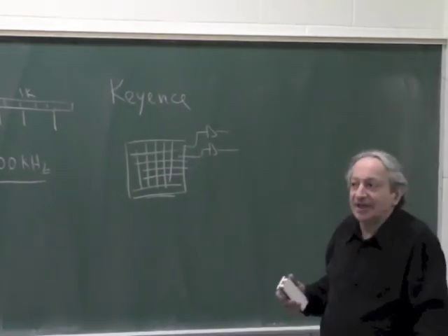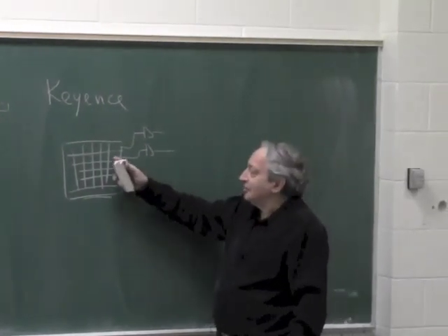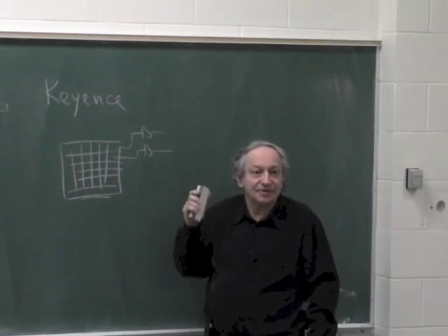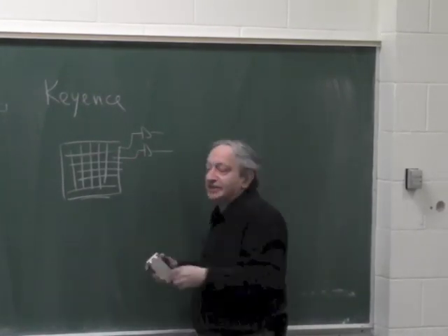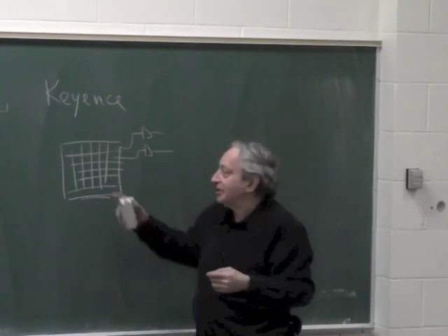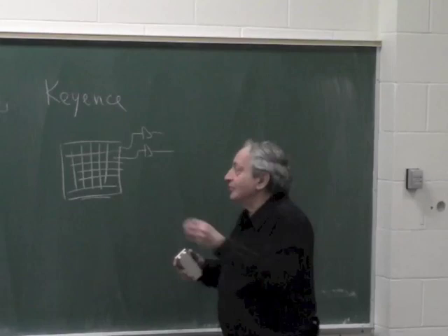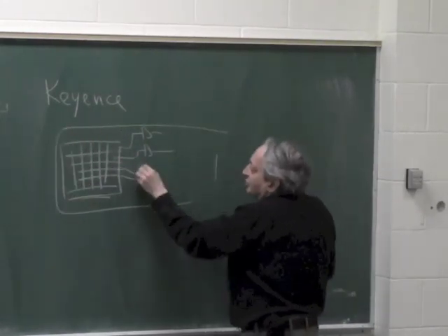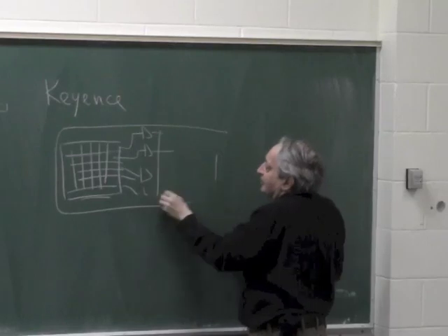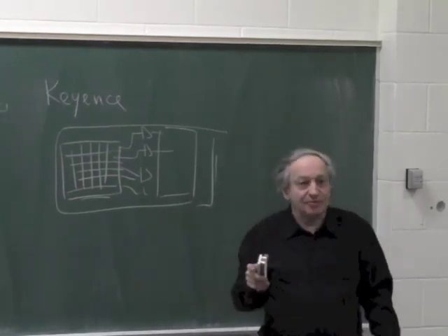And then you can make an array processor connected to a camera in which each pixel is brought out. Because in the silicon, 10,000 wires are not a problem. If you had to bring it out with a connector with 10,000 pins, it wouldn't work. But if it's all one silicon chip, and these are brought out on the chip to the amplifiers, and then you have an array processor, it's all on one chip, that's very doable.